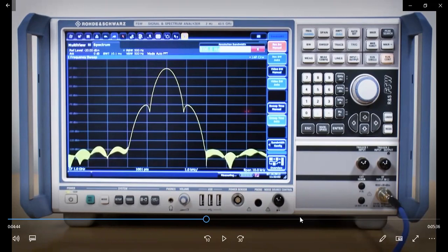So how close frequency points you can identify, or properly separate their amplitude levels. The amplitude levels are varying, but how well you can actually recognize the separation in the amplitude levels at close frequency points. So this is the quality of resolution. So as you reduce the whole span, you have better resolution.